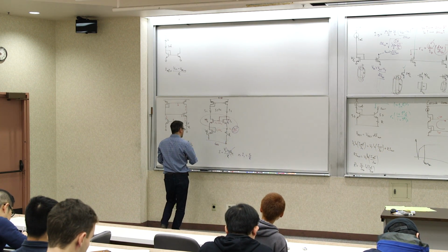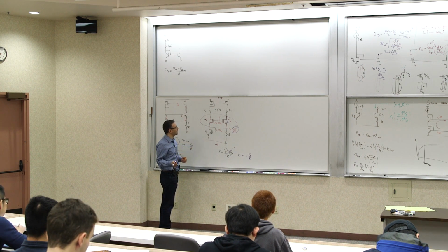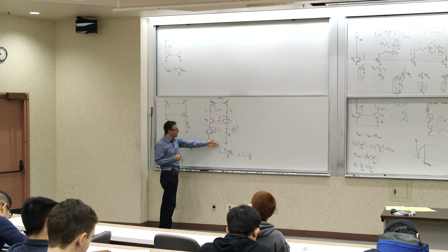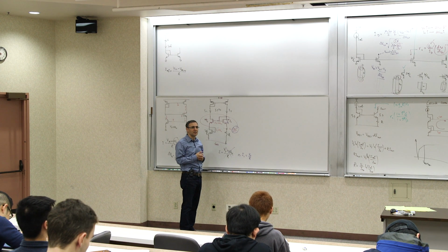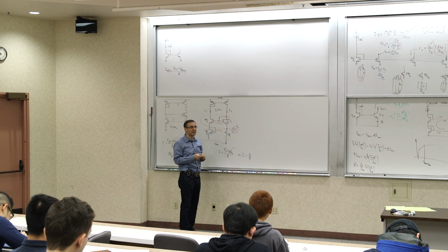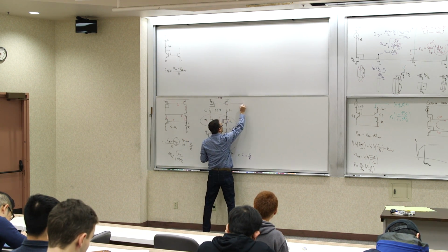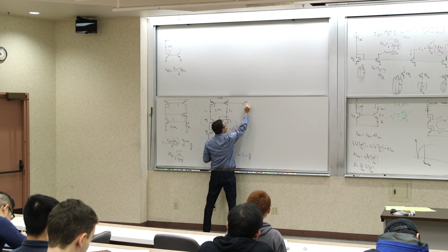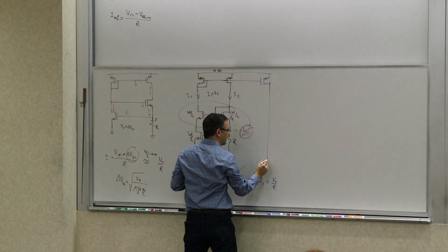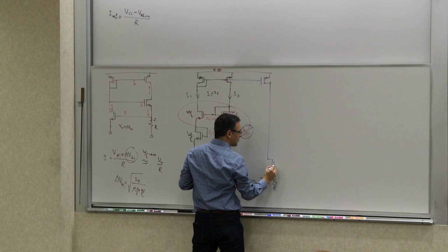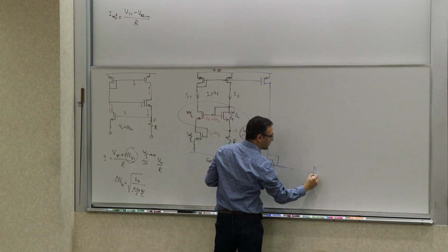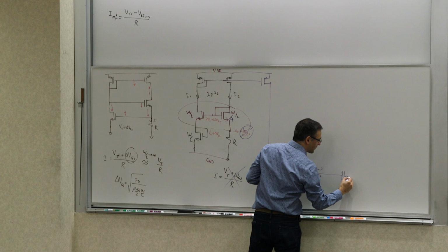And now you may say, okay, well, what do I do with this? Let's say we made this thing. It's VT over R. How do we use this? How do we make our reference current? Well, this is our reference current, right? Because I can replicate it one more time here, and I can feed it into my distribution branch of my current mirror and current generation network.